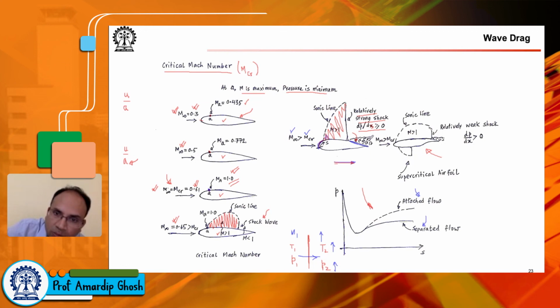And you have flow separation due to this relatively strong shock creating a ds greater than 0. So the flow separation creates the pressure drag due to flow separation kind of effect due to the wave, but this pressure on the front surface actually gets exaggerated because of compressibility effects, and we will see that.